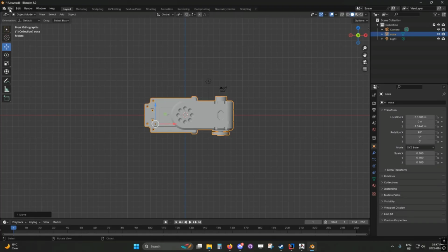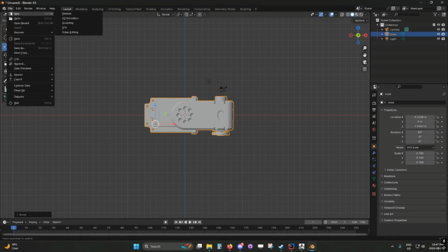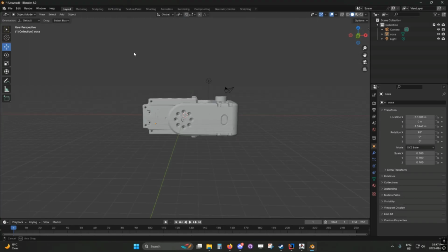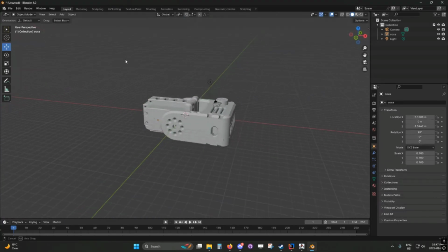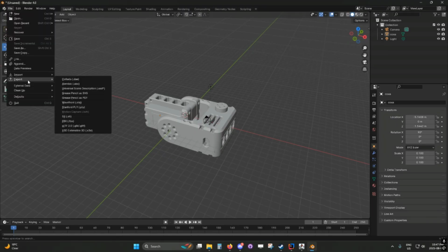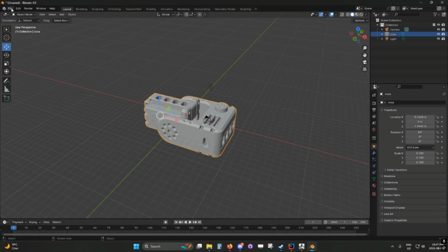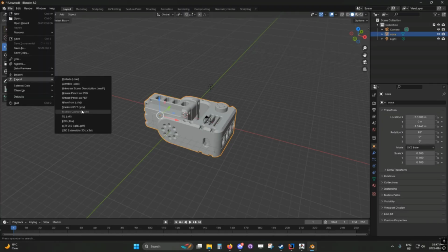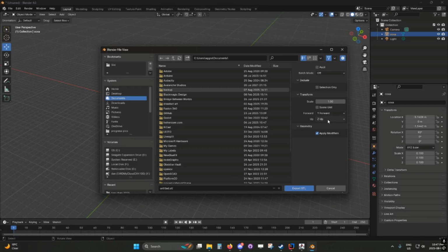The axis coming out at us is the z-axis, right? Based on the thing we said. No, there's a whole shenanigan that happens because by default Blender has Z going this way and Y going that way. But when you export, there's another. Sorry, I have to have this selected. File, export to STL. There's this whole thing about which way is forward and which way is up, and this makes me insane.